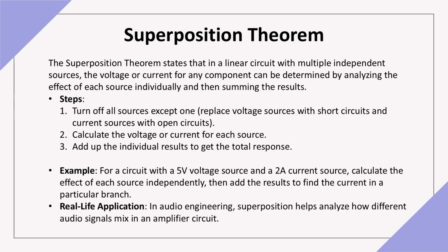The superposition theorem tells us that in linear circuits with multiple sources, we can analyze each source independently and sum the results. This principle is particularly useful in audio systems where multiple signals combine. Let's consider a practical example. In an audio mixing console, where multiple input signals combine to create the final output, superposition helps us understand how each input contributes to the final mix signal.